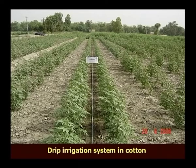This is the view of drip irrigation in cotton crop. Here the dripper to dripper distance is 30 centimeter and discharge from each dripper is 2 liter per hour. The crop is being grown in paired rows and the distance within the pair from row to row is 60 centimeter and distance between the pair is 120 centimeter.